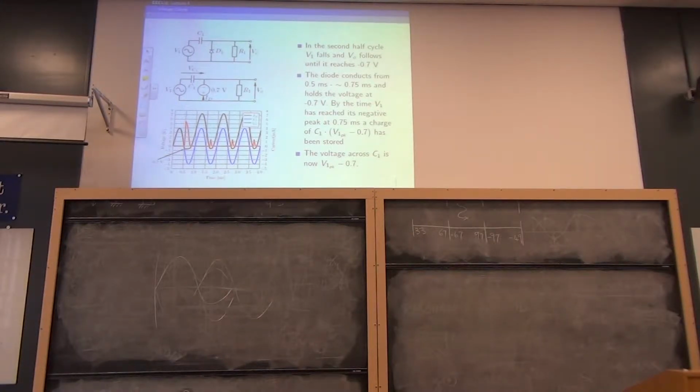And the diode conducting clamps the input voltage. That's to say, it charges up the capacitor. So a large current flows in D1 onto this plate of the capacitor, because this is the more positive end, this is the more negative end. So what we've really done is closed a switch, essentially, between a battery and a capacitor.